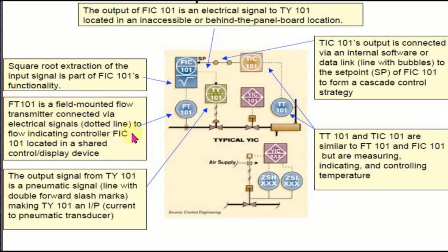So dotted line to flow indicating controller FIC101 located in a shared control display device. We have also here the output TY101.